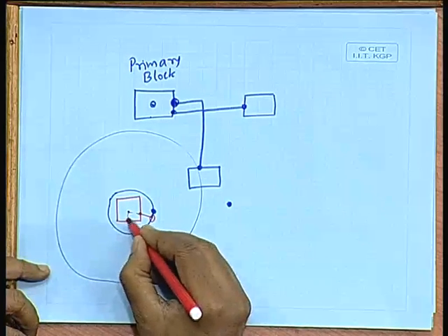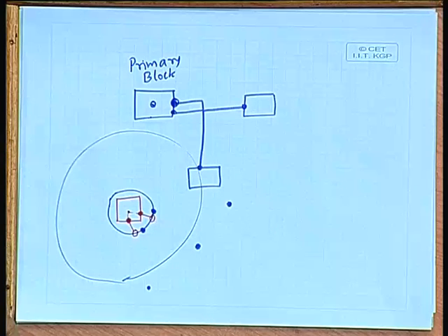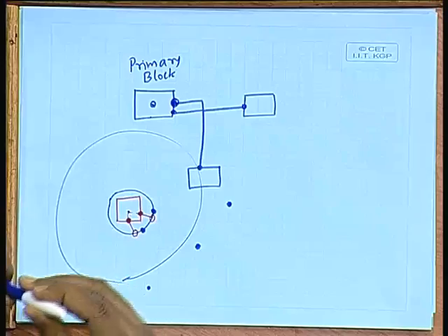So, you will say that the pin will be here and the pin will be here. This topology mapping and concentric circle mapping are similar, with the difference that concentric circle takes all nets at a time, but this takes one net at a time, and this can handle multi-terminal nets.